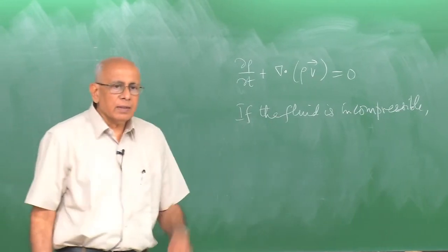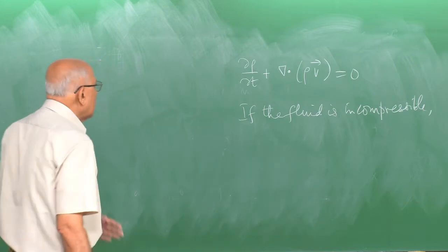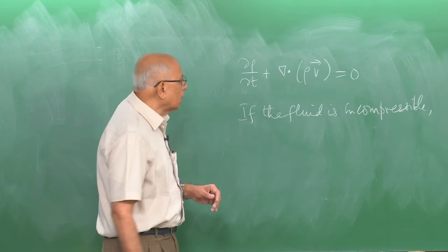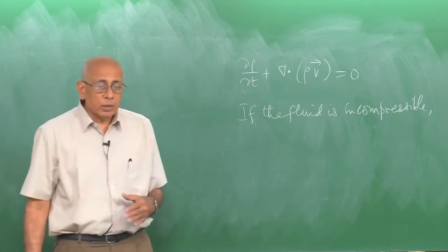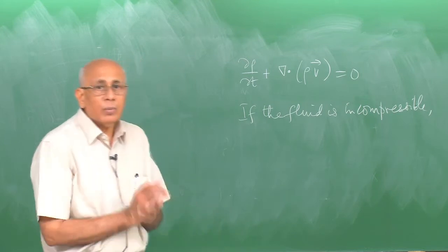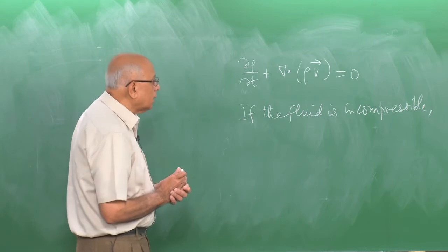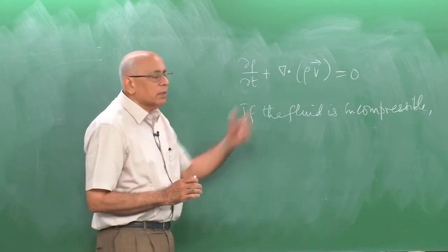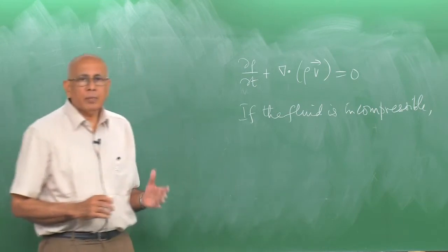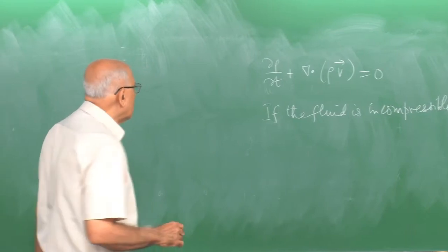Even in the case of gases, as long as you are not dealing with very high temperatures, or very violent fluctuations in the density due to different temperatures, or going near the speed of sound in the medium, so that you have shock waves and so on. As long as you are not dealing with such velocities or such conditions, then for velocities much lower than the speed of sound in the fluid, essentially the fluid is incompressible. Even a gas is essentially incompressible when it is in flow here.